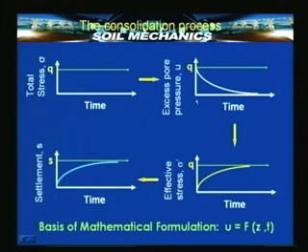The pore pressure itself will be equal to q at t equal to 0, but with time it will gradually get dissipated and ultimately it will become 0 at t equal to infinity, and correspondingly the effective stress will be 0 initially and will gradually increase, and at t equal to infinity it will be equal to the applied stress q, and the entire applied stress would have got transferred as effective stress to the solids.